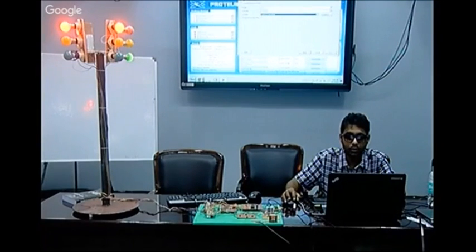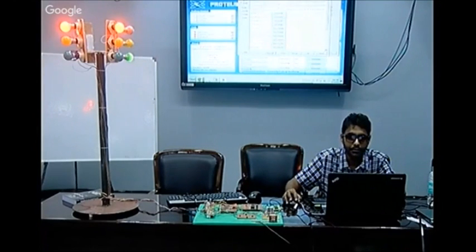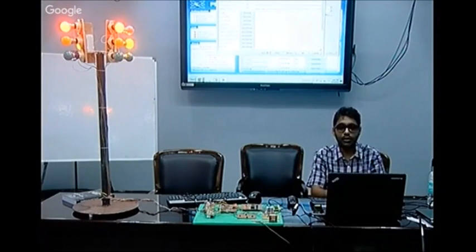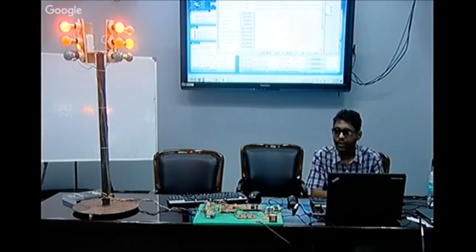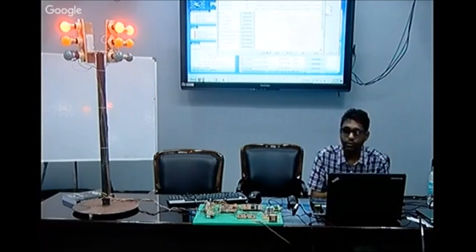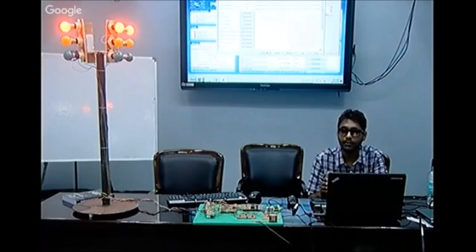This is the compiler section. It's a button for the compiler. You have to select this one, and for example, if you installed the Keil software parallelly, then it will be installed in the C directory. Then you just have to select the path of that installation folder, select it here, and press OK. Now your software will be linked with the Keil software.